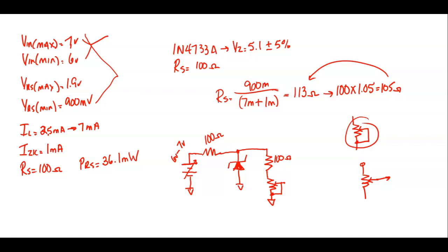If I want to measure total current, then I can measure what? The voltage across that resistor without breaking the circuit. So you learn real fast that to measure current, we can measure it directly by breaking the circuit and putting our meter in series, or if we can find... Yeah, that's the guy. That's the series resistor. And what's constant in a series is the total current, right?